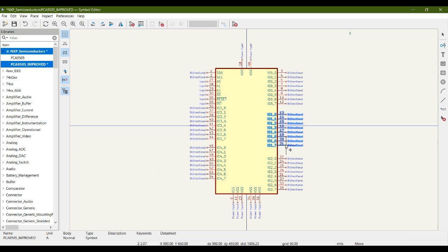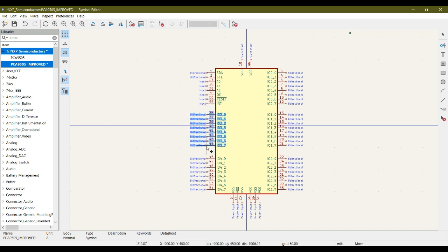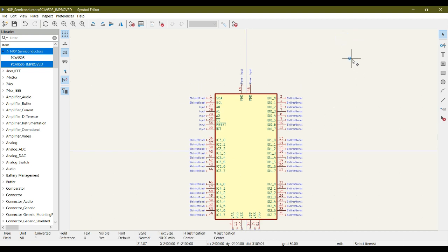Yes, this is the center of the symbol, so select over here. Now you can similarly do over here, select these pins, hit M and move this bank 4 towards the bottom, and let's select bank 3, hit M and move over here and hit save to save our symbol. So let's move this, select this U designator, let's place it over here.